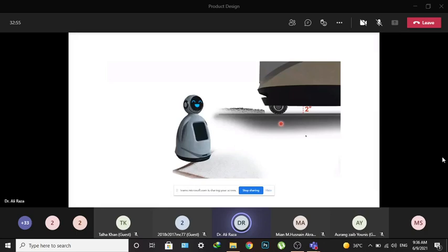On top of that, the clearance is really important because the robot has to move inside the apartment. So how those apartments are structured generally, what the hindrances are, if there is a carpet, what the height of that carpet is which it has to handle, and on the basis of that, there was quite a lot of discussion on what is going to be the most appropriate clearance with the ground. So it was discussed that we're going to keep it at around 2 inches.